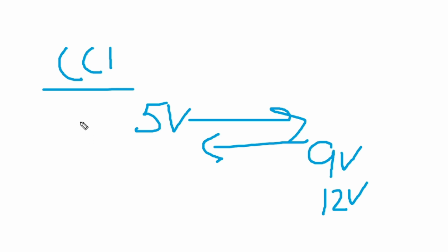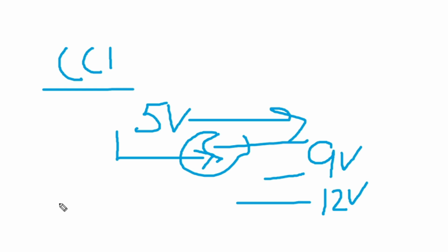You can say the charger is a source and your phone is a sink. Through signals coming from your charger, a handshake, your phone requests 9 volt or 12 volt for fast charging.